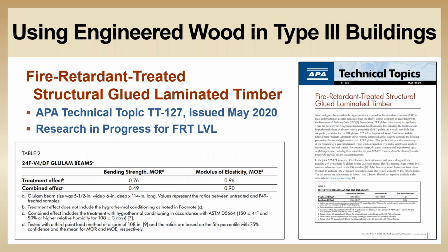So bringing this section to a close, I'd like to reinforce some of the main messages associated with FRT glulam that you should keep in mind. You want to make sure you take the design reductions when specifying FRT glulam. And again, you check with the treater for the specific design value reductions for their specific product.